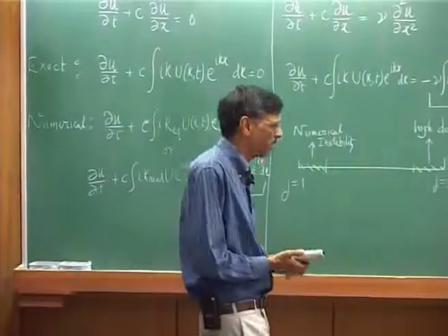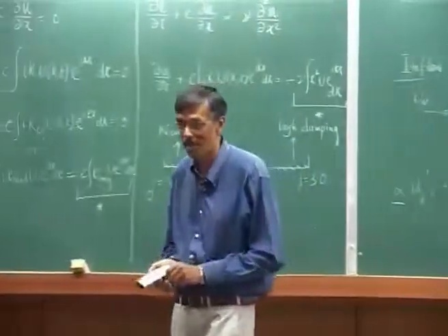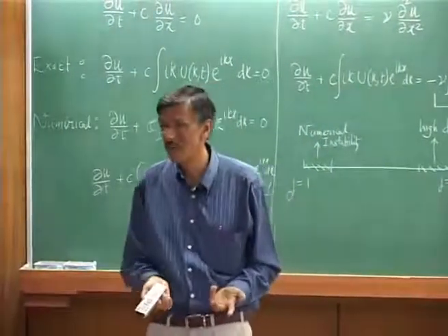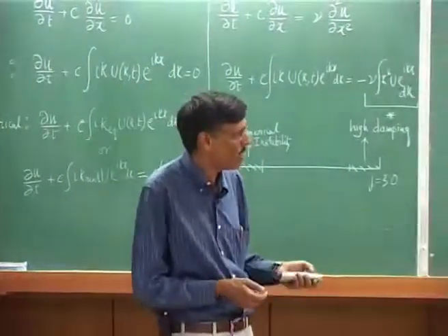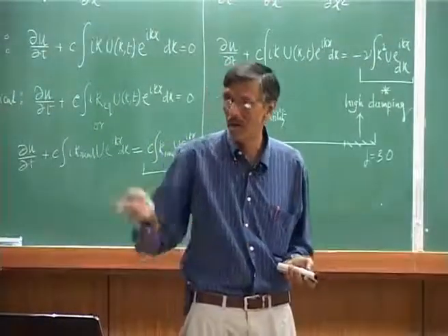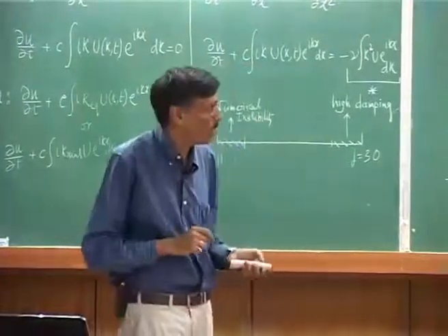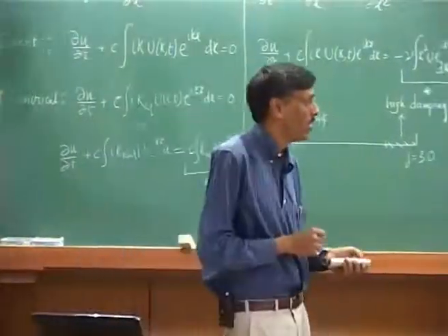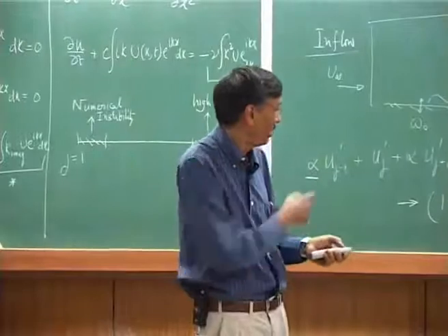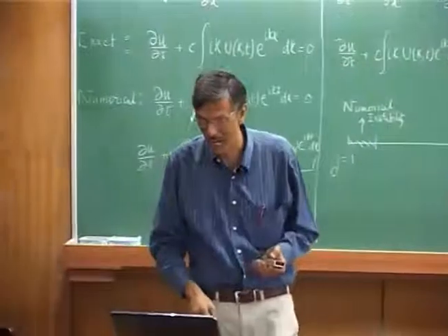Now, what has happened in this optimization issue? We have only satisfied the equality of u prime. So, what is the order of the scheme? Order of the scheme is, well, it is second order. So, even within the compact scheme, earlier we showed that compact schemes are much superior to the explicit scheme. Now, within the family of compact schemes, we are noticing that if you do a careful optimization, then you are going to get a much better resolution of this second order scheme as compared to the sixth order scheme proposed by Adams.